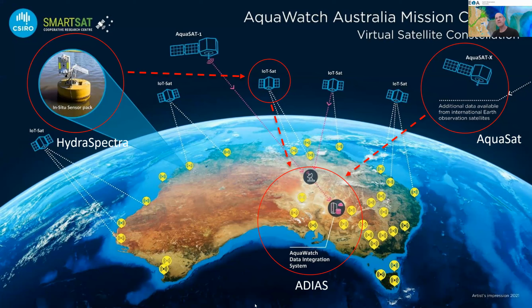Complementing the Earth observation satellites, we'll have a dispersed network of in situ sensors. And these sensors might contribute any data, water quality parameters that aren't detectable from space. So they might detect salinity, pH, dissolved oxygen. It might be weather stations. In some cases, we'll also be using imaging spectrometers in those in situ sensor deployments, either to provide information about the light reflected from water and what we can directly infer about the chemistry, or as a source of data for calibrating the satellites against.